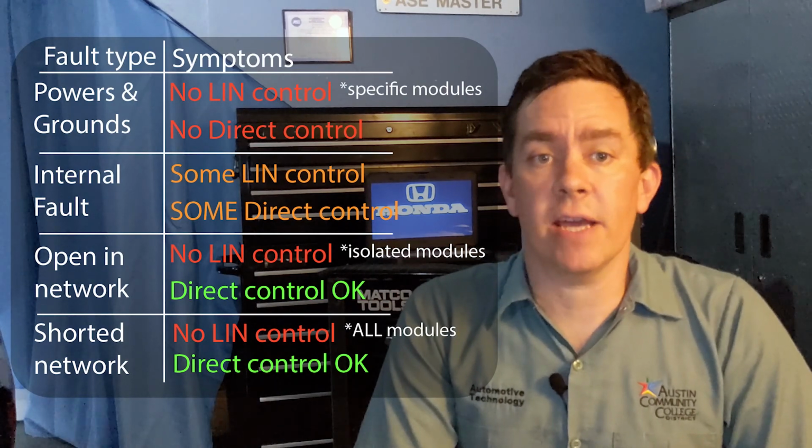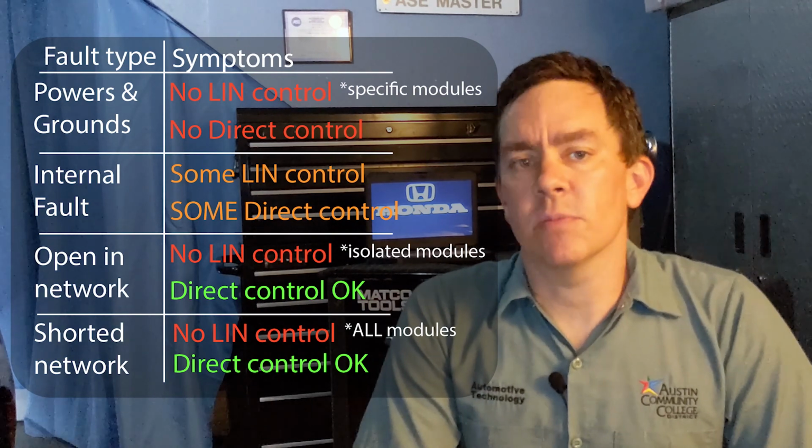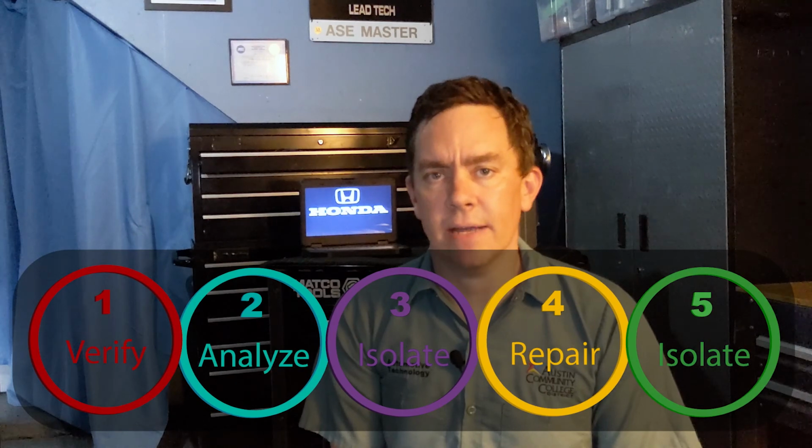But the fact that control units don't all act the same doesn't mean we can't use these techniques across all vehicles. Remember, symptoms that affect some control units point to opens in communication lines, power and ground faults, and defective control units. Contrarily, symptoms affecting all control units indicate shorts in communication lines, and on certain networks, any of the types of fault we mentioned. Symptoms alone aren't going to be enough to pinpoint the cause of a fault, but in most cases, they're going to help us narrow down the possibilities enough to begin electrical testing. Like anything else, if we understand the operation of the circuit and the system, we can progress through most failure scenarios using our 5-step diagnostic process.